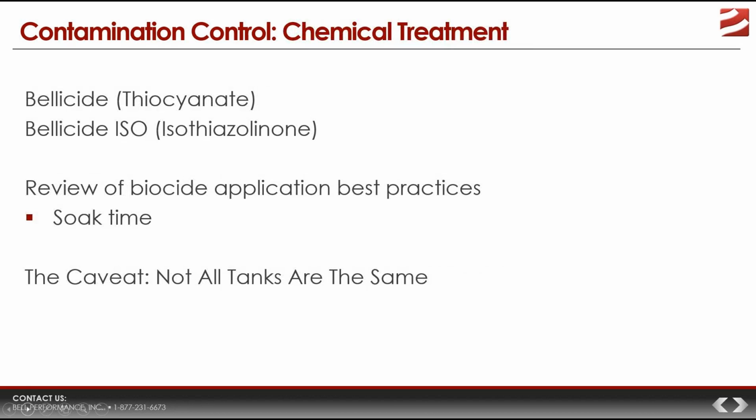And then the last thing is chemical treatment. You've gotten as much water out as you think you can. You've removed as much biofilm formation as possible, but you know that you didn't quite get all of it. So now you treat with a biocide.